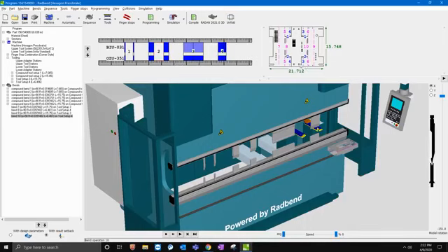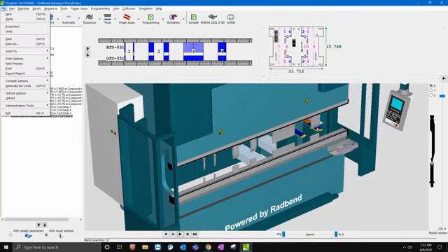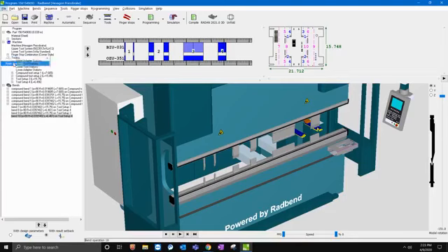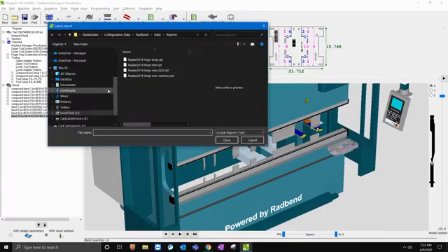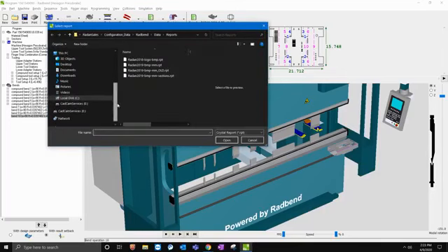And you'll notice that my dimensions here may have changed on this one. I can't remember what it was. But here we can also do a print preview, right? If I do a print preview, I can create a setup sheet, because sometimes we want a setup sheet so we can send it out to the guys on the floor.